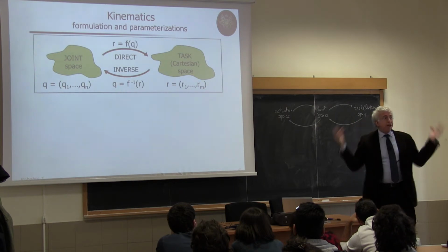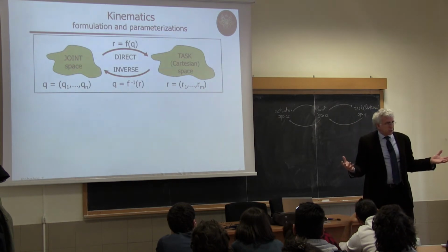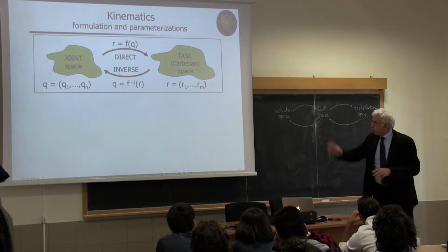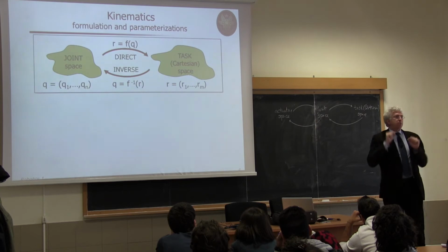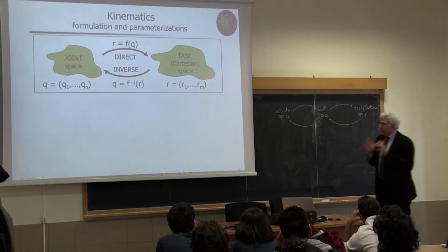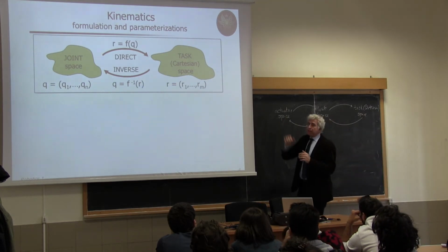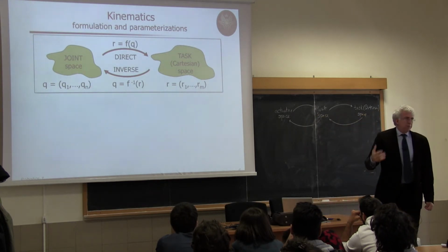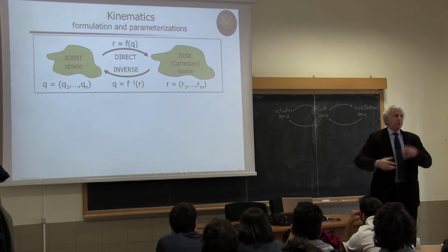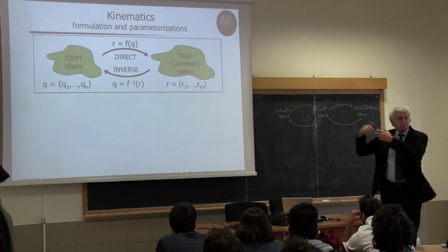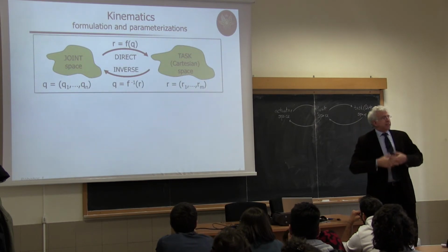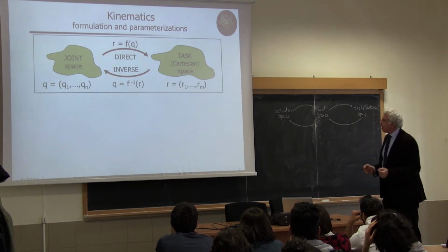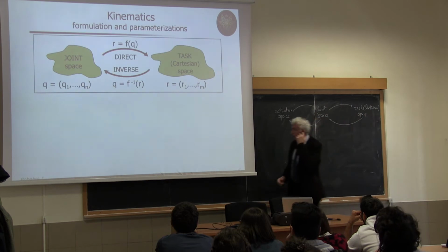But you can imagine a variety of other tasks, not strictly remaining in the Cartesian space, and this is why it's useful to be a little bit more general. The basic joint to Cartesian space transformation, which is the classical kinematics, will always be needed anyway. But out of that, or combined with other information, you can build what we call the task kinematics for the task at hand, and related to the specific robot.